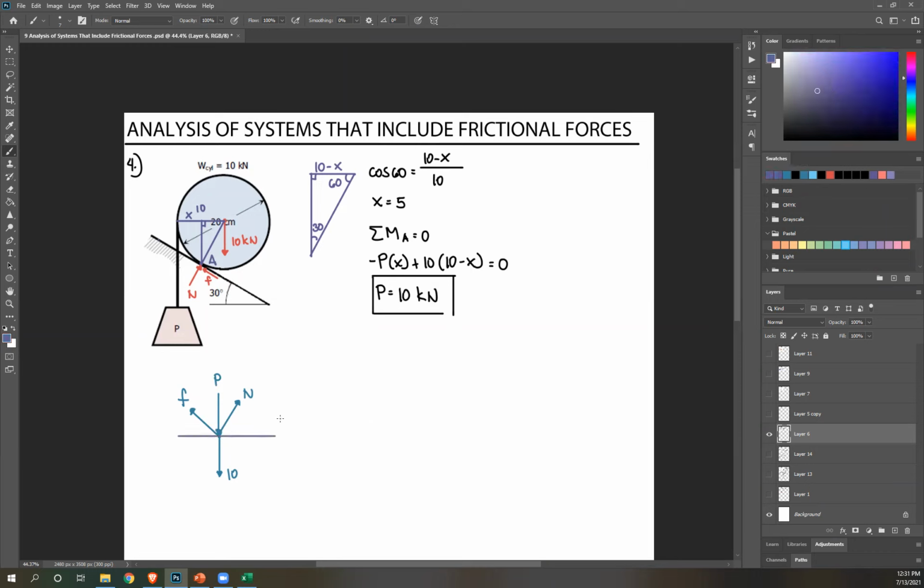Okay, next figure out our angles. What is this N? Now we already know, right? Angle of N from the horizontal is just a complement of the theta, angle of your incline. Complementary of that, that's just 90 minus 30, so this is 60. Okay, that has the same slope or same incline as your surface, so this is 30. And that is your free body diagram. And then from this, you can create your equations. Let's start with summation of forces X.